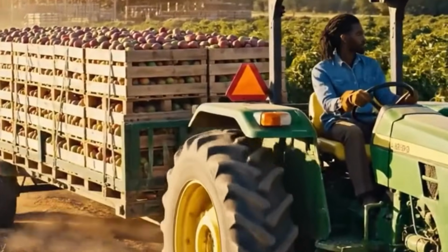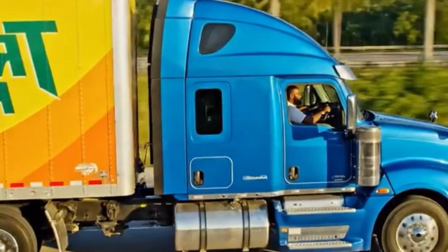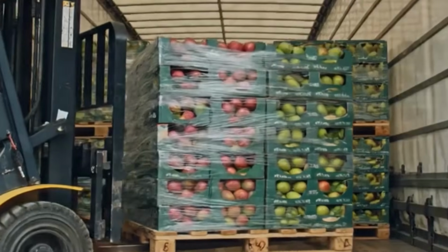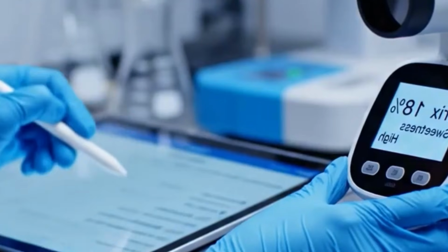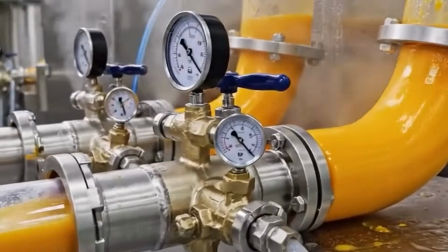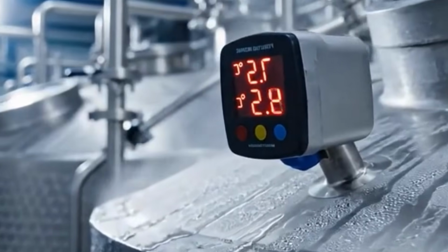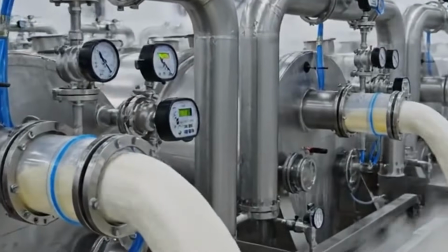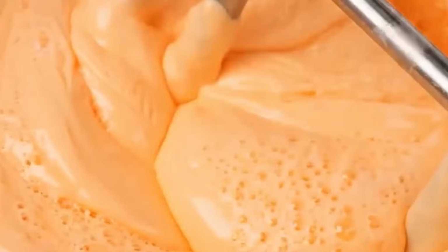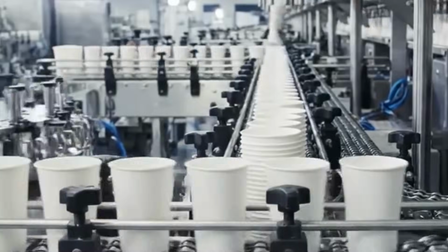Hardened products are conveyed to automated carton packers. A vision system identifies each container's orientation and positioning. Robotic arms equipped with suction grippers or mechanical clamps group units into clusters and load them into pre-erected cartons. Cartons are sealed using hot melt adhesive or tape, then labeled using a print and apply labeling system. The label includes SKU identifiers, lot number, date, and logistics barcodes.